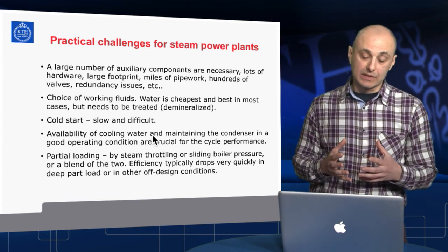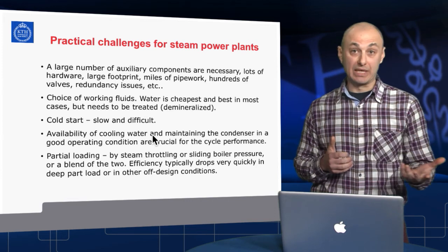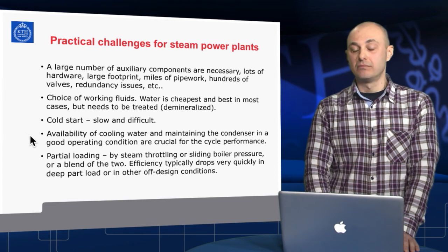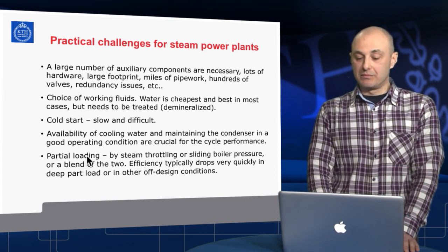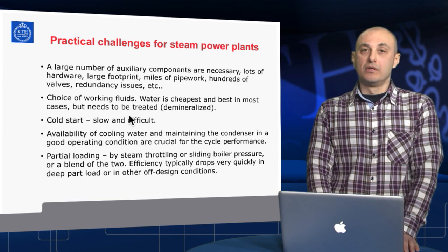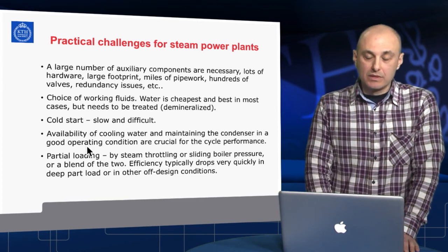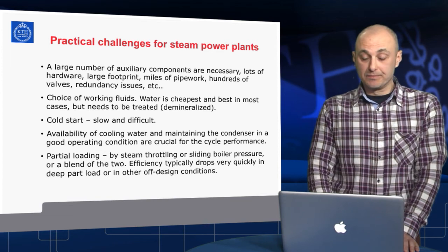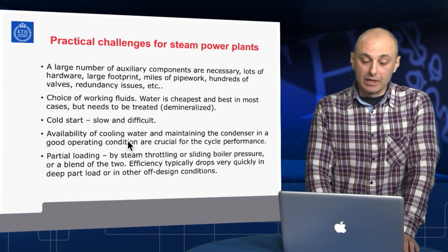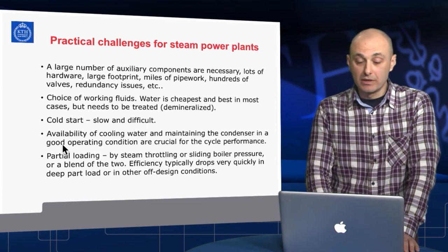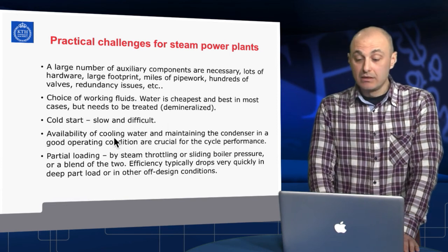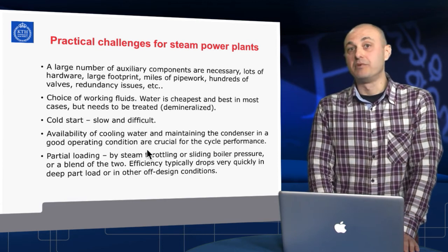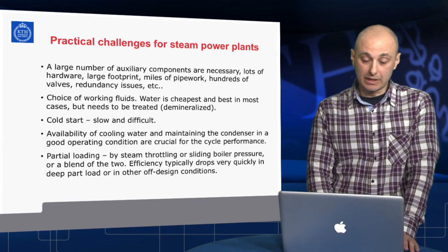Now, decreasing the size of that heat exchanger, which is one of the biggest hardware devices, matters. If you are in an environment which is already arid, you would like to avoid using cooling water as much as possible, or save it as much as possible. Providing the cooling, whether it would be a cooling tower, or a lake, or a river, or a sea, well, it's a lecture of its own, but you must think about it before you start composing the entire cycle.